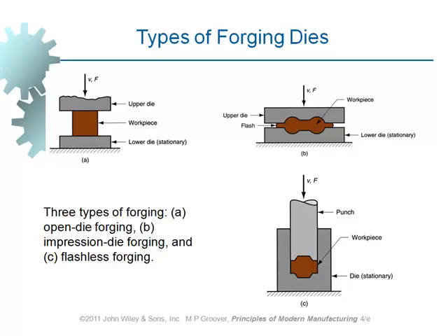And as it was mentioned in the video clip, sometimes you cannot bring it to the final shape and geometry because in forging process you cannot achieve close tolerances and high surface finishes. So you may still need to subject it to minor machining operations in order to bring it to the final shape and geometry. However, the magnitude of the machining required will be significantly reduced because material has taken the initial shape by making use of other processes such as forging.